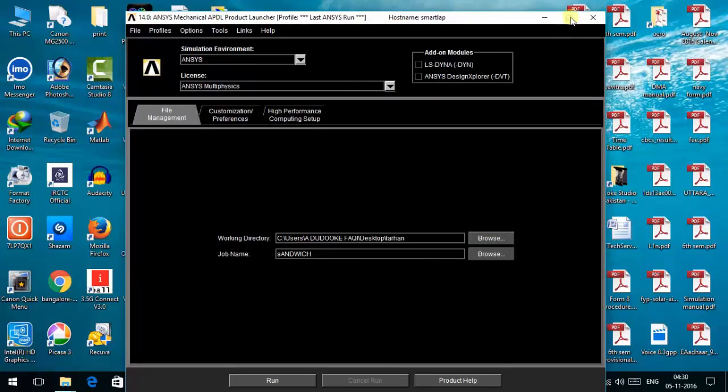After this, set your working directory. I've already set it. If you don't know how to set your working directory, please watch the previous video. I've explained it there. And give the job name. Let me give this as rectangular plate with cutout.